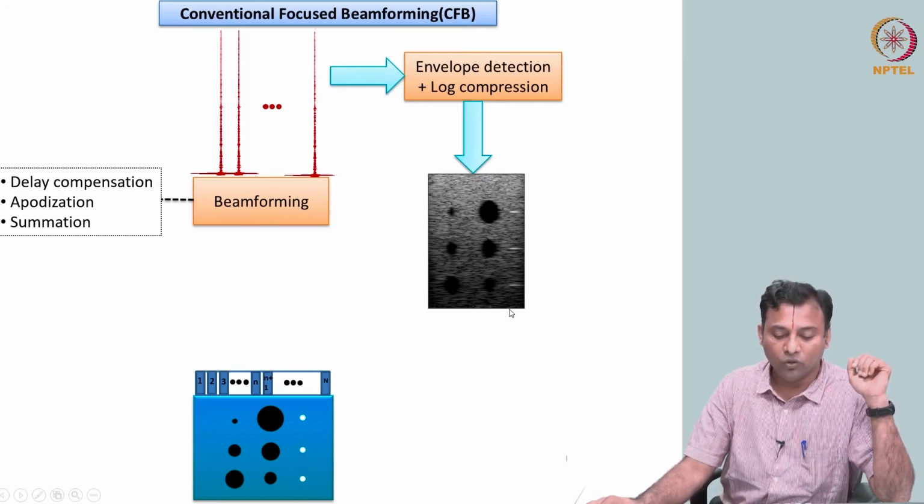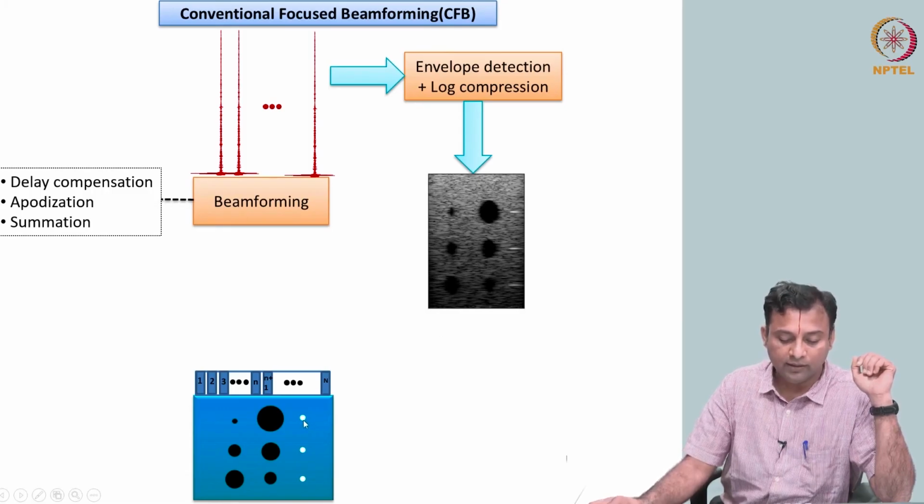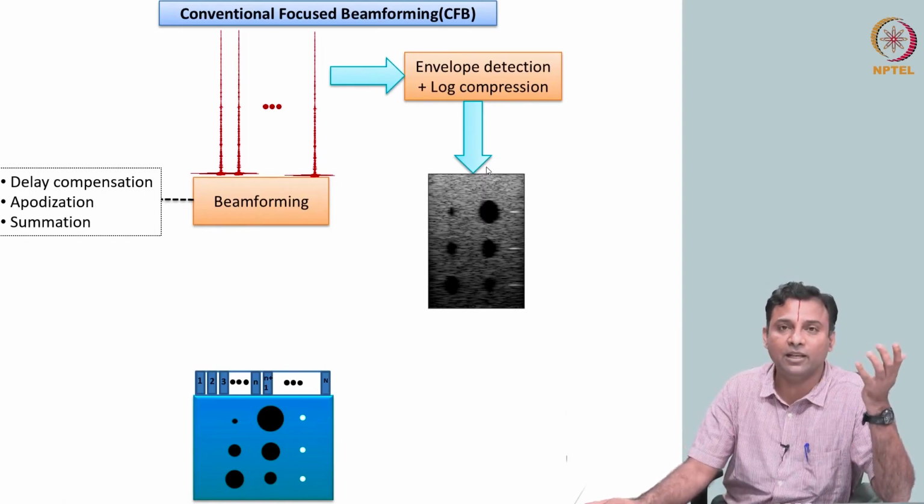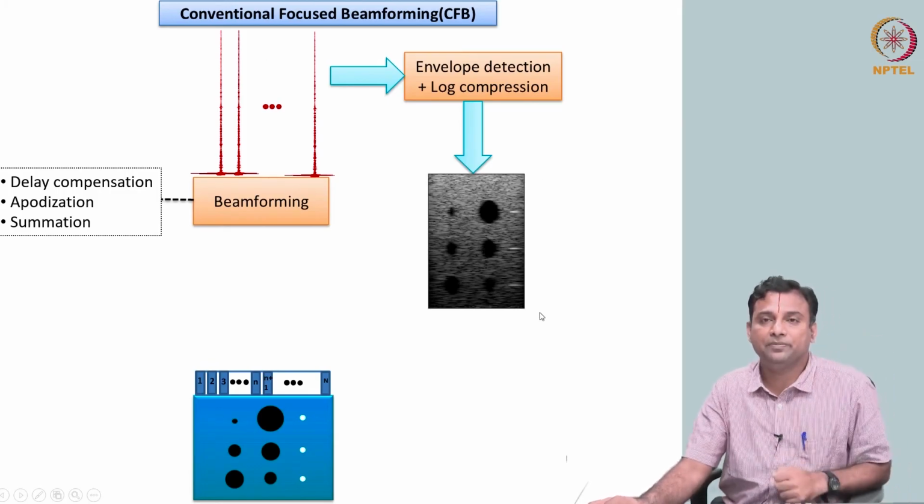Notice more or less the structure is there, but it has its own resolution limits, and you can see that it's becoming difficult to see here. This round is now not really round because deliberately it was stopped in the end. If you use much more sophisticated signal processing, we could improve the image quality further. But the idea is that now you are visualizing how we start with the physics, have instrumentation, and manipulate the instrumentation in the digital beamformer case to get an image.